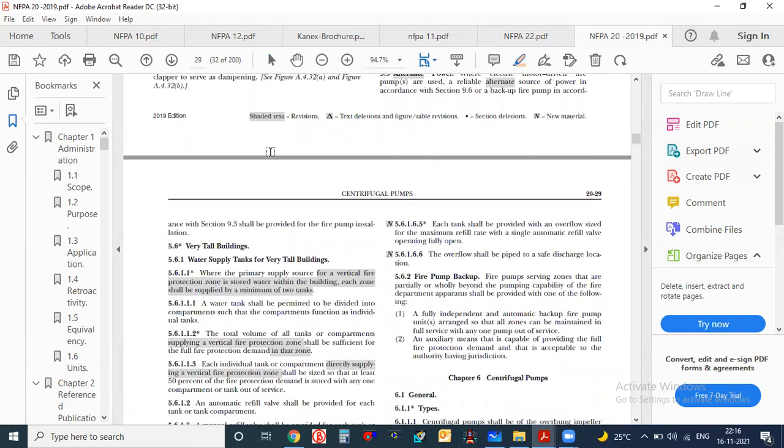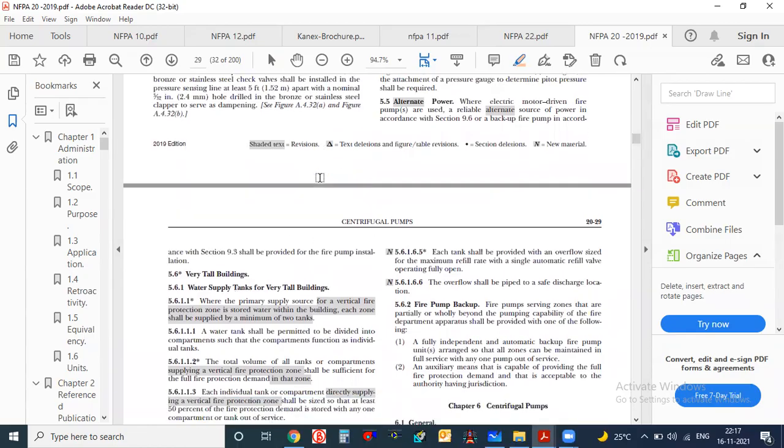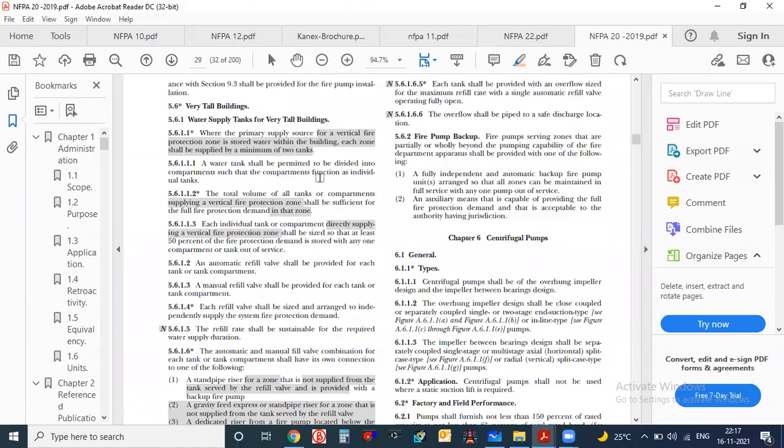Hi sir, how can we find out the fire pump head? Fire pump head. We have done the hydraulic calculation, no, for that only. So with the help of the hydraulic calculation only we are getting the fire pump head. So whatever PSI value we got, that is the head only. Whatever pump we are going to use, based on our routing, we have to get the head actually.